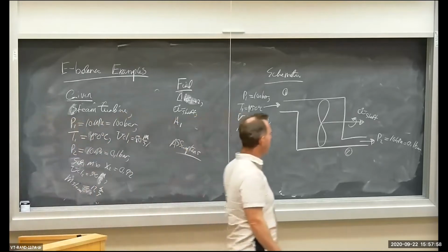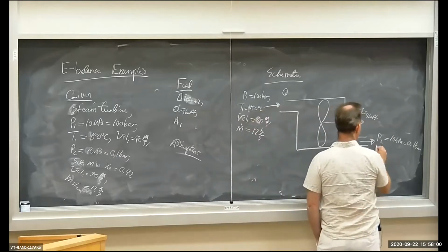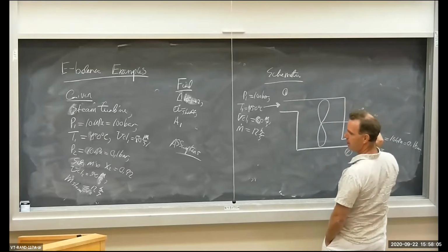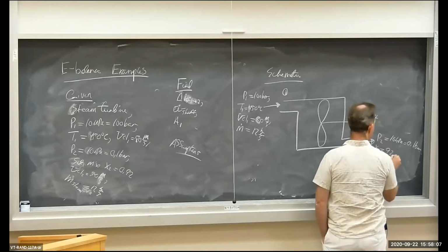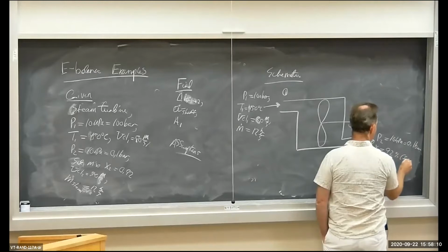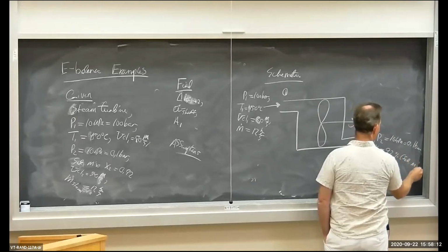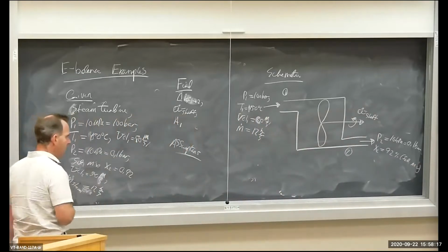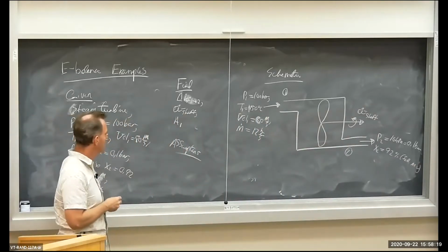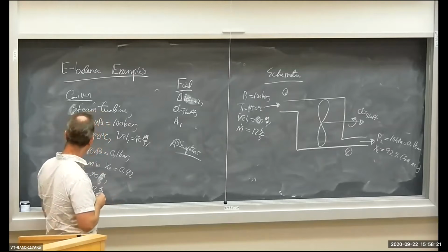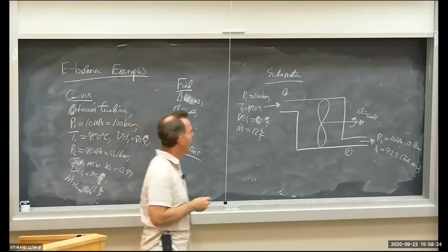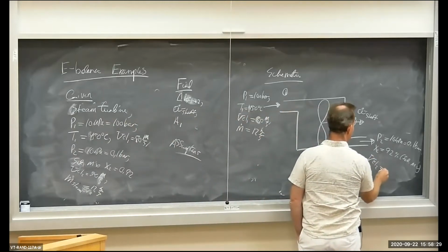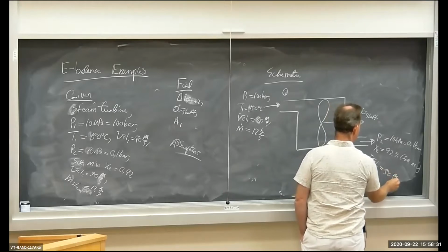And we're also told that the exit state is a saturated mix, with a quality of 92%. A superheated steam condenses down to a saturated mix primarily of saturated vapor, but there's a bit of liquid in there, and pressure falls by a factor of 1,000. The outlet velocity, VEL2, goes down to 50 meters per second.